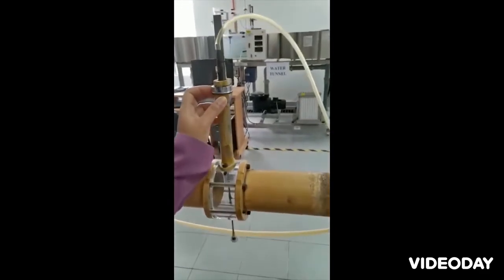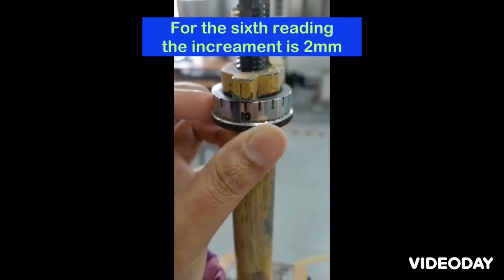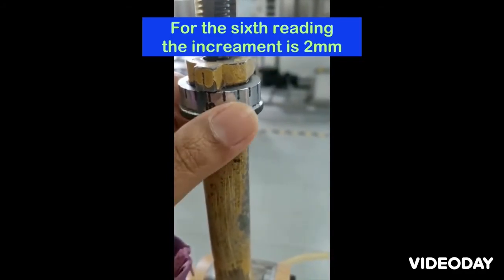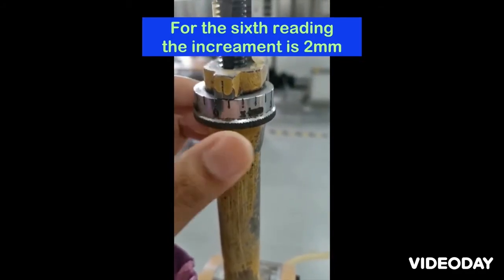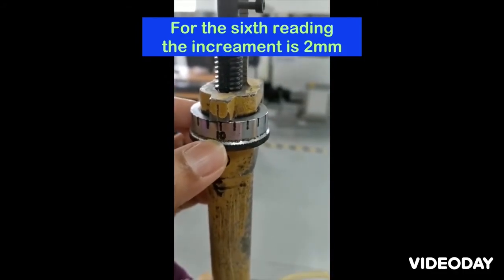For the next 3 mm, you need to repeat until 5 mm. So each increment is 1 mm. For the 6th reading, you need to increase the increment to 2 mm. So 2 mm means you need to rotate it for the full rotation. If you start with 10 here, you need to go again to 10. That one is the 2 mm.